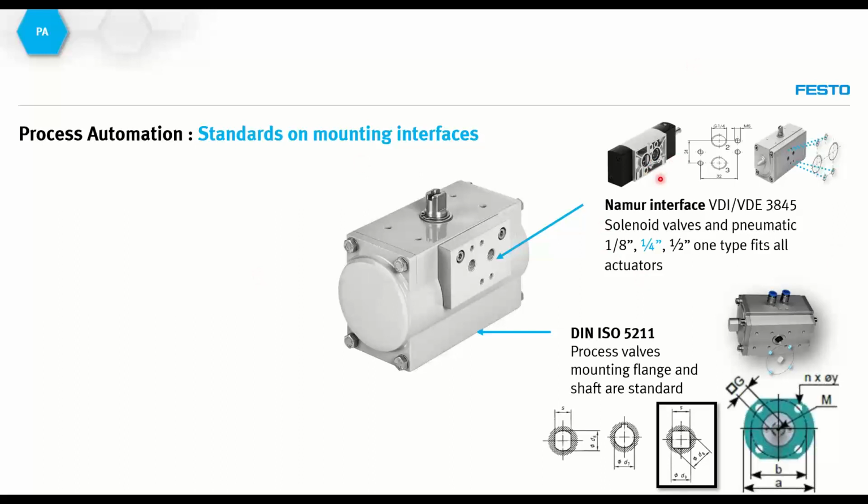The Namur interface is where the solenoid valve is mounted directly on the actuator. Here also to highlight that we have three Namur sizes based on this standard. We have the 1/8 inch, the 1/4 inch, and the 1/2 inch. With these different sizes, we also have different flow rates. The most common size is the 1/4 inch.